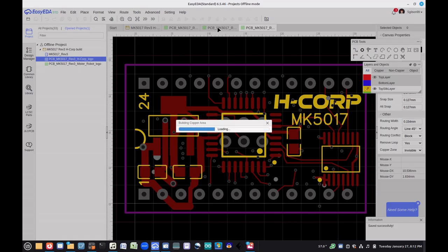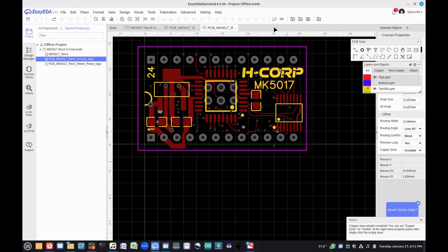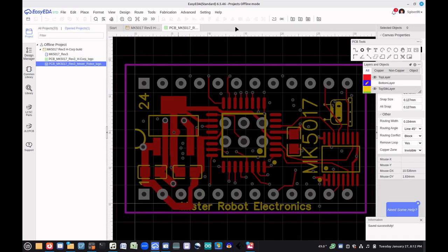And then you go back. Actually, what you do now is you go ahead and close that module that you're viewing. In fact, you can even close the H Corp design. I should also mention, I should back up a little, that you run a DRC check on each layout beforehand, and you should get 0 errors, because once you combine them, you can't do a DRC check.